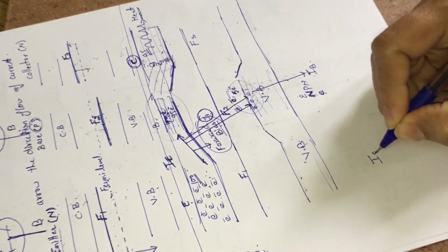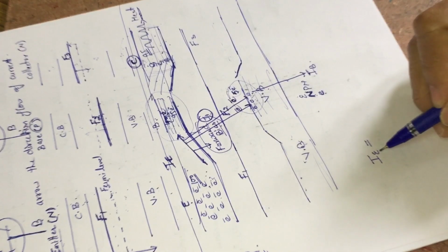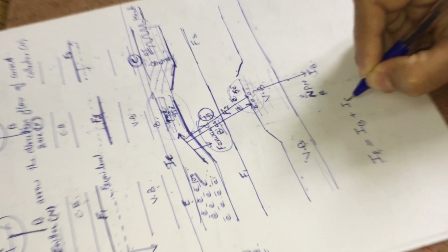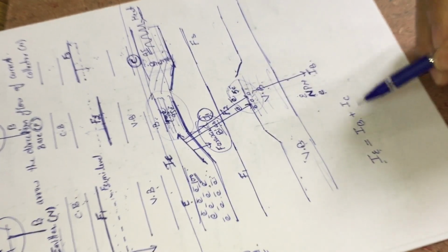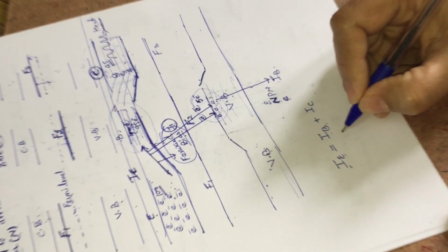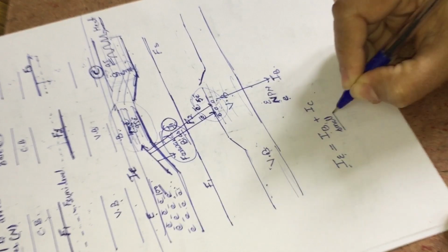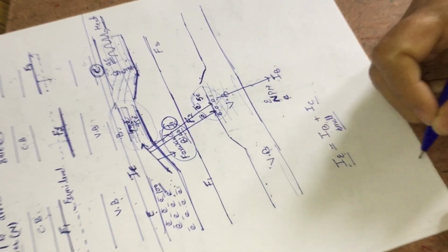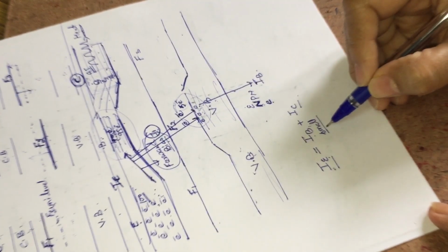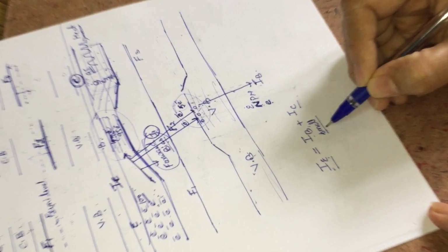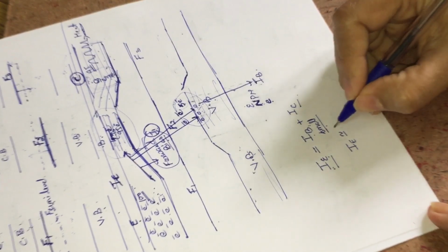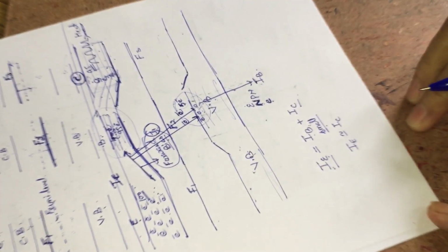And we get that the emitter current is divided into two currents, the base current and the collector current, where the base current is very small compared to the collector current and emitter current. In some of our numerical problems, we take the base current as very small compared to the collector current and emitter current. Hence, in many cases, we take the emitter current as approximately equal to the collector current.